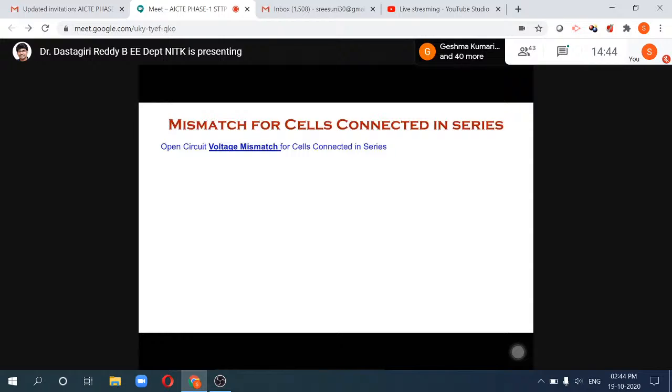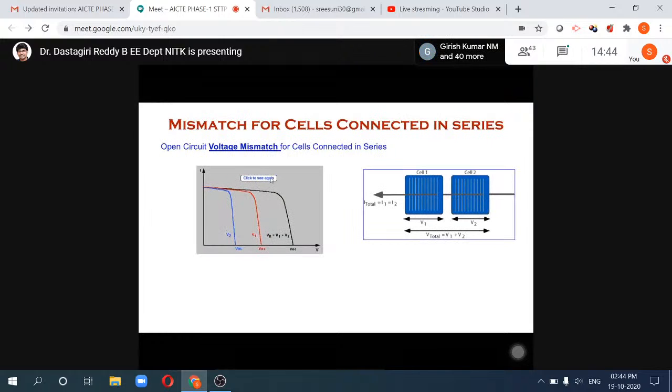So we also have studied this mismatch in diodes, but here it is something different because you have one diode which is already there inside, but the current will be passing outside. So there will be some impact whenever there is a mismatch. We'll see that one. So basically, if nothing is wrong, then you add up two voltages. If something is wrong, then the result will be the reduced voltage. That, in simple words, is what we can say.